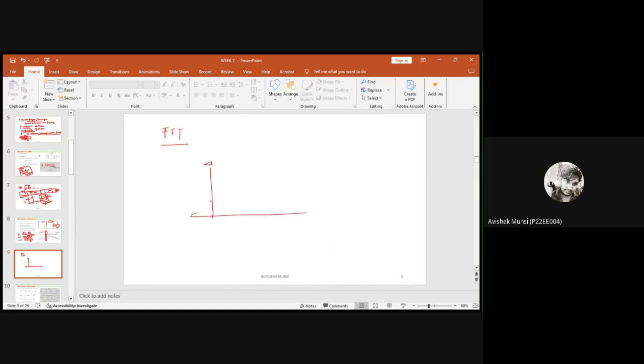fundamental, that is a DC component, and suppose you are switching it at a specific frequency. At the switching frequency there will be some harmonics, but other than this there will be more noise and harmonics introduced into your system at different frequencies, and you need to eliminate these things. This will introduce total harmonic distortion in your system. By FFT analysis, you can check how much disturbance there is due to the parasitics and the noises introduced into the system.